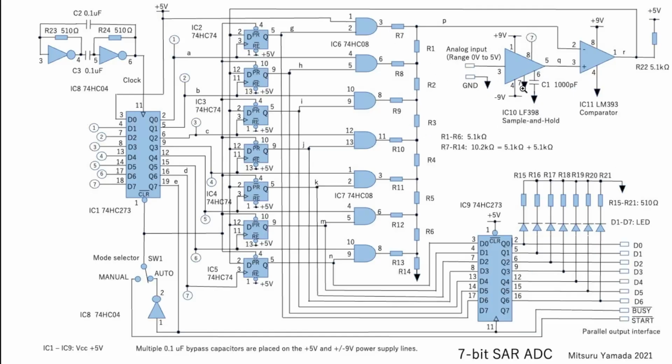And then after it's done, it releases it and takes in a new analog value and does the entire thing again. Basically, how the circuit gets the digital 8-bit value is, first of all, this clock is giving the clock signal to this octal D flip-flop, so it controls the clock of the entire circuit. The circuit takes an 8-bit voltage created from this R2R ladder that I built in a previous project, and it changes the highest bit to a 1.